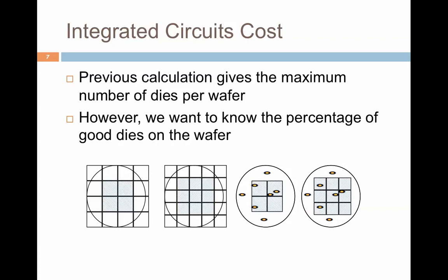So each die will have up to 7 to 9 metal layers, and they will have highly dense components. And all of that is built, right? So you have a lot of etching, a lot of lithography. You will create different wires, those wires are to be connected, and so on. So you will have some defects. Given that we are scaling technology to 22 nanometers and going down to 9 nanometers, we are assured to see several defects in our components. And this is not something that is new. We know this very well.